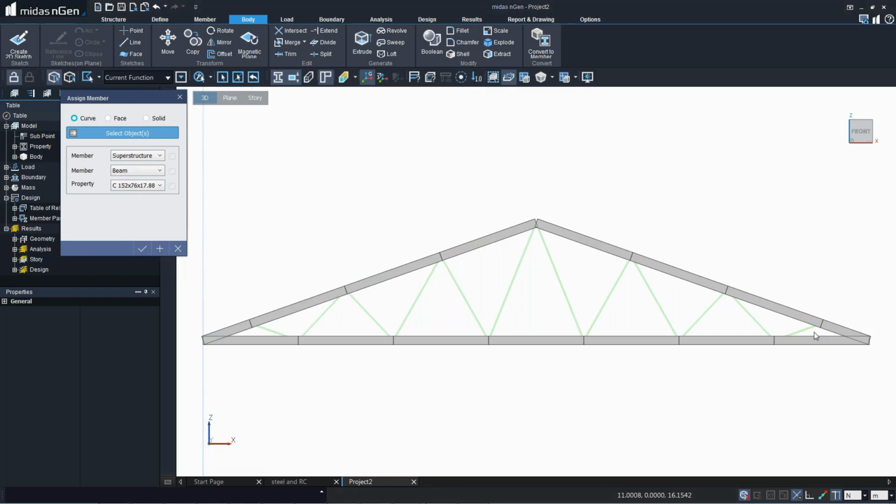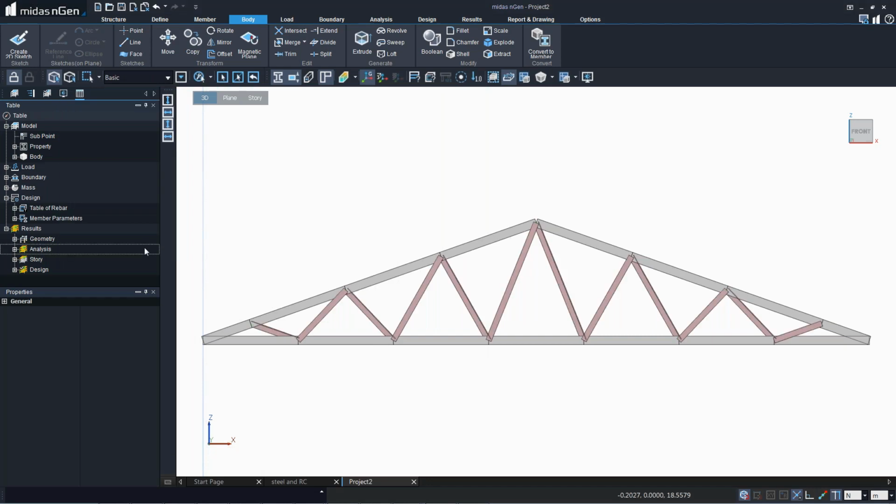And then I'm going to create truss members. So I'll get back to my rectangular selection and select all these inclined lines and convert them into brace type of members. In brace as well, we have got different element types. So we have truss element, beam element, tension only element, and compression only element as well. So I'm using truss type of element and angle section, which is by default available in the MIDAS engine new file. You can of course create your own section properties.